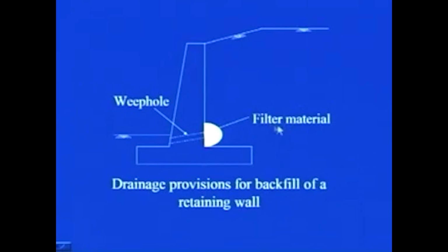Then what should be this filter material? We really have to be cautious that the soil particles which are part of this backfill should not clog this filter material, otherwise its functioning will be hampered.